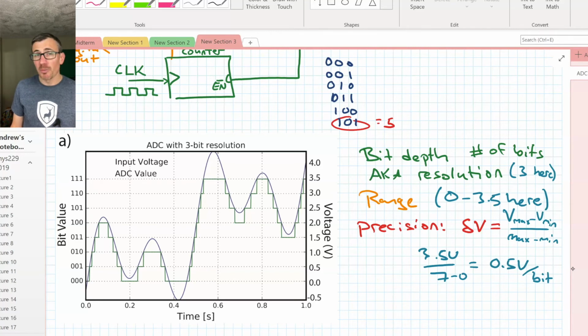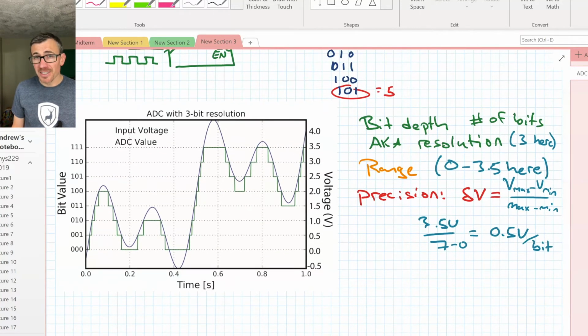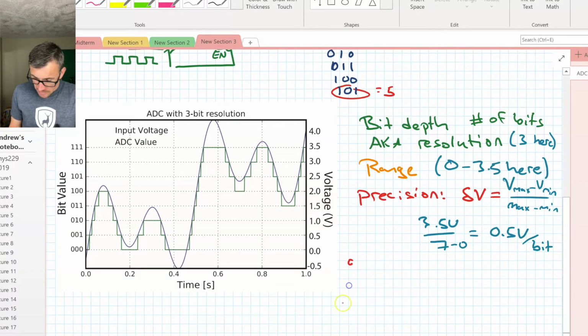This tells us that we won't be able to tell the difference between 0.2 and 0.3 volts. And it's going to give us one part of the accuracy of our analog to digital conversion. So the accuracy that's related to the precision, certainly I should say that the precision causes a loss of accuracy in that we have a loss of information. This range here is what we call digitization error.